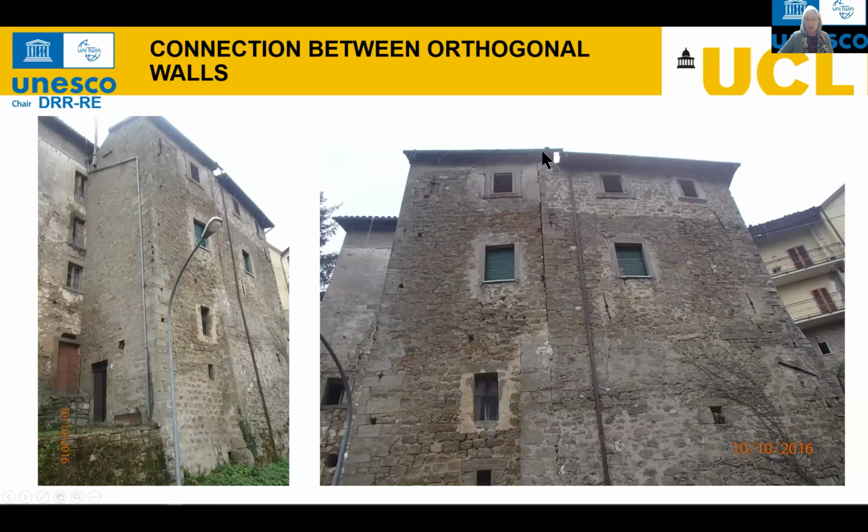how we can recognize them, again, here you can see very clearly for instance, that there are these junctions between these two buildings, and that the building on the left has no connections, the facade has no connections to the party wall of the building on the right, while here there are clearly return stones that connect into it. This side is held with some ties. Here it's held again with some cornerstones, the same cornerstones we see on the left, and the photos on the